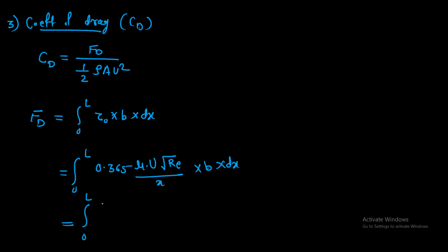So it is integration 0 to L 0.365 mu capital U upon x, and Re is rho U x upon viscosity mu, into B into dx.